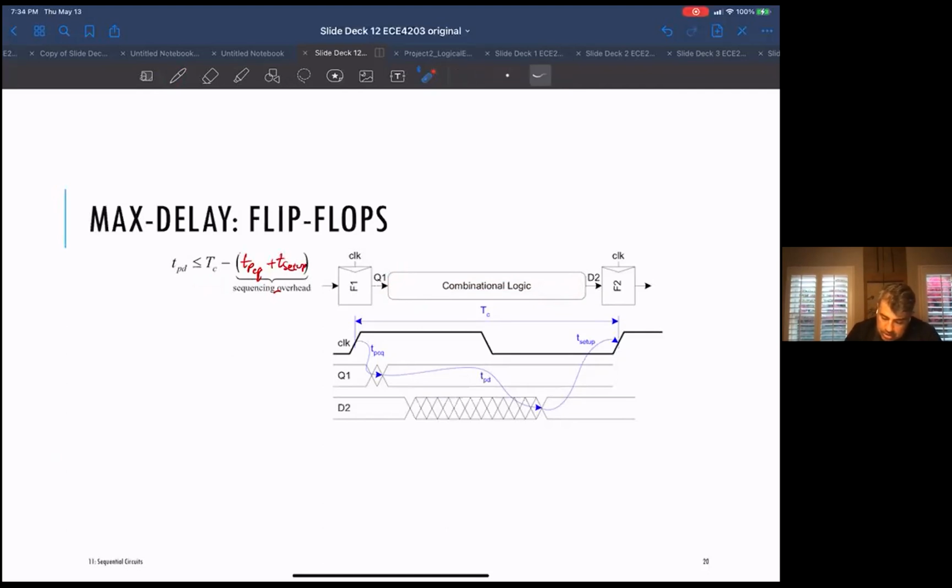So, I guess you can see it in this drawing. Let's say your clock edge goes high, right? From this point, there's a change here. So that's when this happened. The latest that change can happen is the clock-to-Q prop delay. That's the latest change that this Q1 can appear on the input of this combinational circuit.